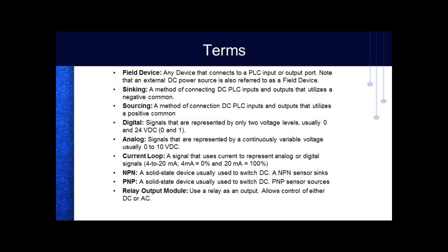So these are some terms, guys, that you need to know, because these are used throughout these manuals when you actually start looking at the manuals for the PLC. They talk about a field device. So what's a field device? Anything that's outside the PLC that connects to the PLC some way is referred to as a field device. Even the power supplies are considered outside the PLC, especially on a modular PLC, so that's called a field device also.